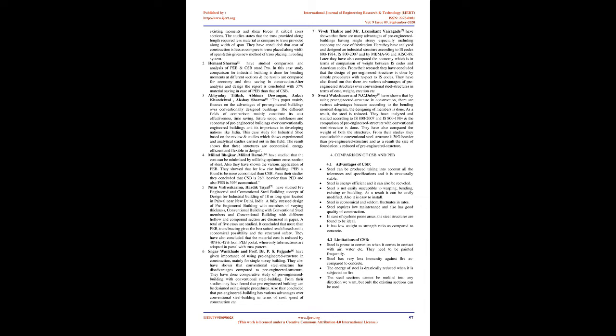3. Pre-engineered buildings, PEB. These are produced in the plant itself. Here, according to the requirements of the customer, the manufacturing of the members is done. The components are made in completely ready condition for transportation. These are then sent to the site and then the erection process starts. The manufacturing process doesn't take place at the site. The pre-engineered buildings are normally constructed for offices, shop fronts, warehouses, etc. Here the extra amount of steel is avoided because the sections are tapered according to the bending moment diagram.